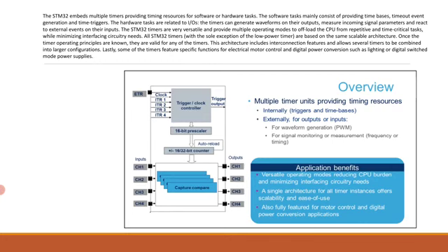All STM32 timers, with the sole exception of the low power timer, are based on the same scalable architecture. Once the timer operating principles are known, they are valid for any of the timers. This architecture includes interconnection features and allows several timers to be combined into larger configurations. Lastly, some of the timers feature specific functions for electric motor control and digital power conversion, such as lighting or digital switched mode power supplies are also available. So some of the